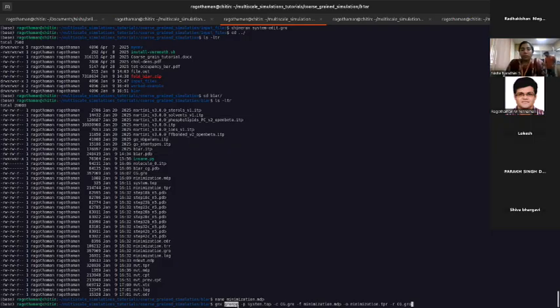So this grompp will take all the inputs that you have given as a gro file and the instructions that you are giving via the MDP file and prepares a TPR file which can be used for simulating the system. So here, in the -p flag, you can mention your topology file, then the gro file, the input gro file which you generated after adding water molecules as well as ions, and you give the instruction file, and finally the output TPR file, which can be used for the simulation. And this is the reference gro file, which can be the same as the file that you give here.